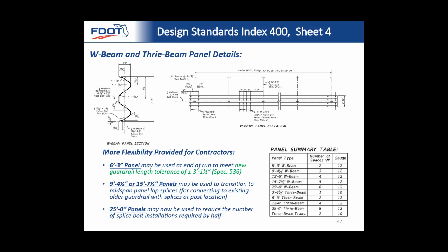So essentially, we don't have to have maintenance governing our maximum length of panels. And when contractors use 25-foot panels in construction, they could fit those on their trucks just fine. They end up using half as many splices, and that results in a lot of man-hour savings. So contractors are really happy about going to 25-foot panels. It's just a lot less work to assemble and splice all these things together.